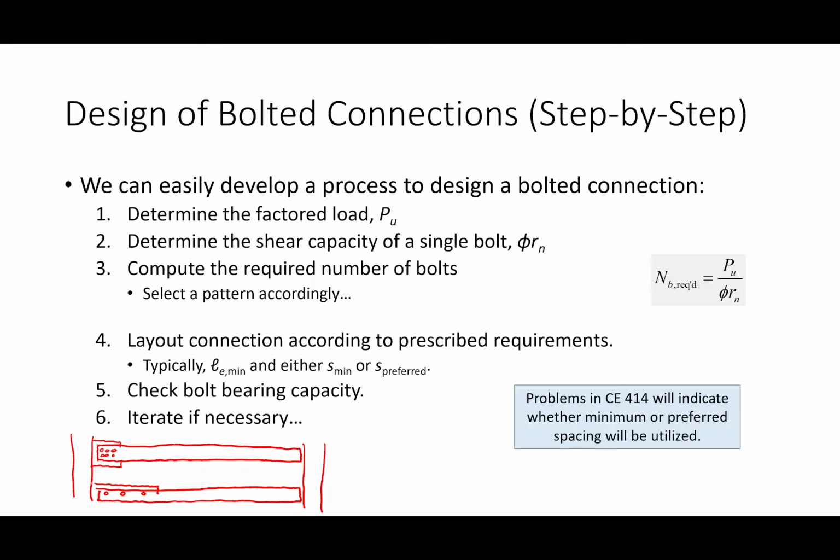So the point I'm making is that which connection plate is more expensive, mine or yours? Yours, right? So having a connection with maximum bolt spacing and maximum edge distances is just going to result in a connection that's more expensive. Does that make sense? So we typically try and go with minimum spacings and minimum edge distances to create a more economical connection overall.